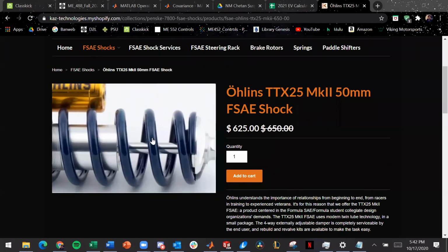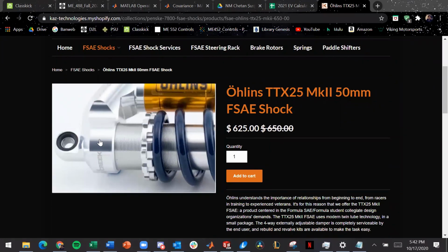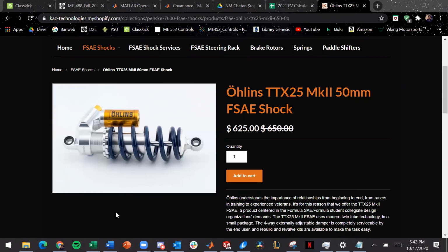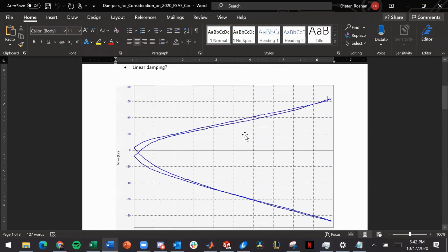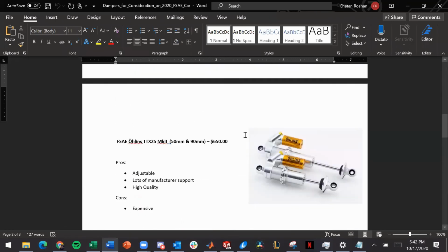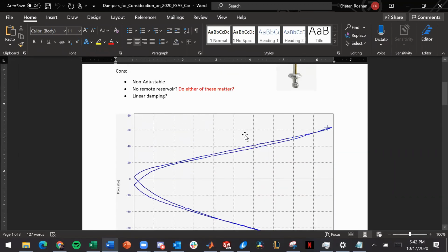We also get to choose the springs and dampers for our car. Springs absorb the energy from an applied force, and the dampers dissipate that energy so that the car doesn't oscillate up and down. There aren't any FSAE rules that constrain us. The only rule that we have to follow is that we are required to use a spring and damper system. So far, we have a variety of dampers and springs to choose from. Some cost a lot, and some are very inexpensive. We also have the option to reuse our old ones from our last car.